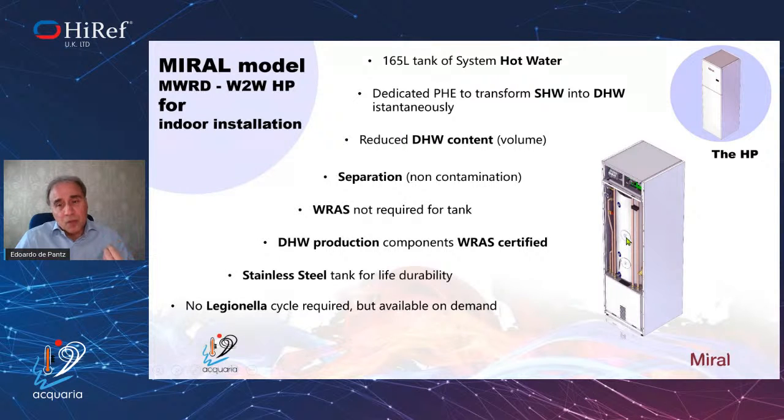The domestic hot water is being produced by an external heat exchanger, external to the tank but inside the unit, obviously, so that the domestic hot water is produced instantaneously when there is a request. In this case, the tank doesn't need to be brass certified because it contains only technical water.